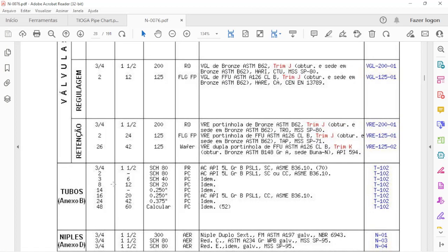My preliminary tube calculation was 4 inches, so between 3 inches and 6 inches. In fact, instead of using a schedule 10S for my process, I will need to use a schedule 40. With this information, I can return to my calculations and verify whether I am still meeting the sizing criteria.